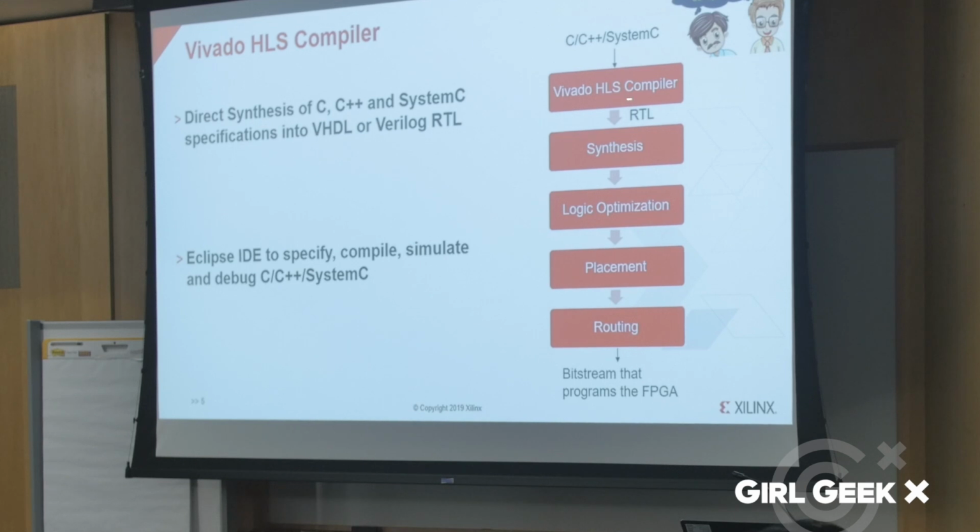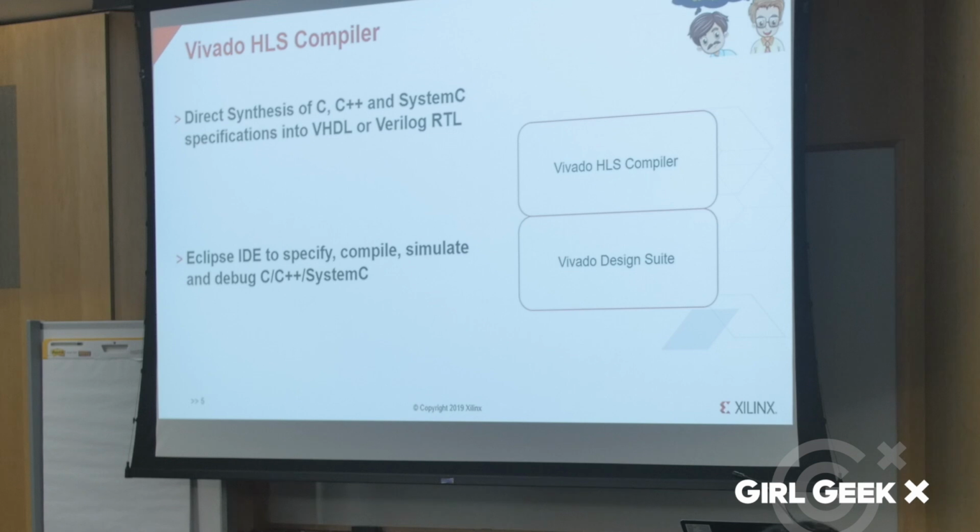And that's where our Vivado HLS compiler steps in. The HLS compiler provides an Eclipse IDE and allows our customers to design and develop using our products. The Vivado HLS compiler can be thought of as sitting on top of the Vivado design suite. So once the C++ is converted into RTL, then we feed it into the Vivado design suite and generate a bitstream. And that allows us to provide a comprehensive solution for people starting with C, C++, or SystemC.